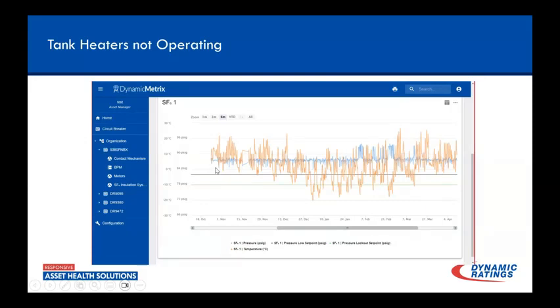But let's say it had been at 80, which is not that uncommon, these would have all gone into alarm. We would have seen alarm points at all of these, at which point we would have gone out. We would have topped this breaker off.